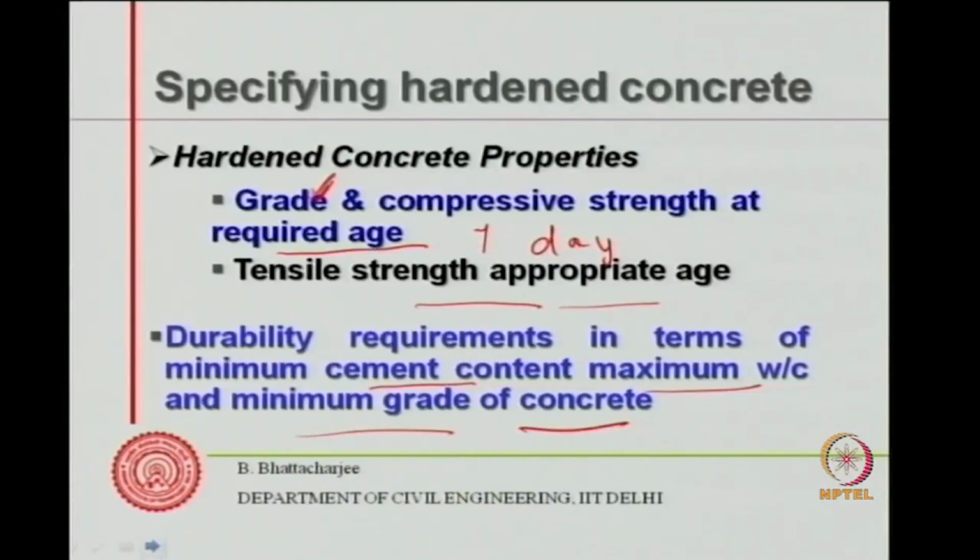For example, where we want to do early demolding, right? Say a pre-tensioned precast system where I would like to apply some pre-tension to the concrete. In such a situation, I might require high early strength.